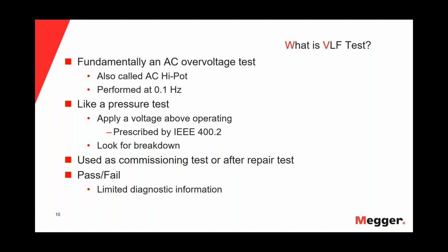What we want to do during a VLF test is to convert into a fault the severe issues in the insulation or the accessories of my cable. We use the VLF test as a commissioning test or after-repair test, and it is a go, no go, or pass fail test. So we will have limited diagnostic information during the VLF test.